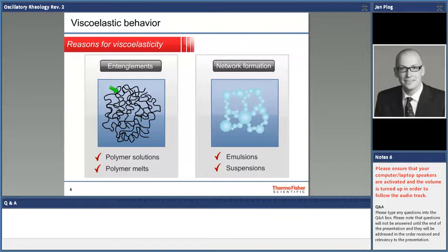You have a too elastic polymer melt at a certain characteristic speed in the extruder, you will have die swell behavior. You will have shark skin. You have a food product that is too elastic, it will feel slimy, or you will have problems to swallow it. So no matter what kind of products you are researching on, elasticity is always something bad, usually.